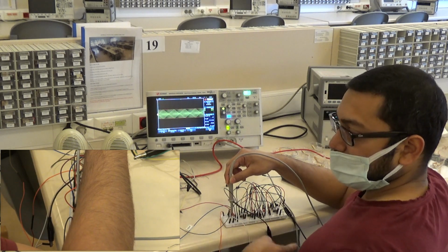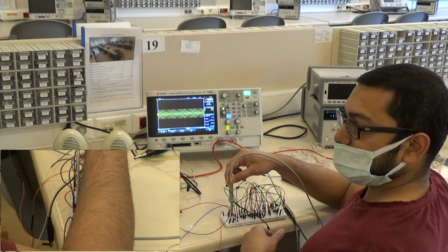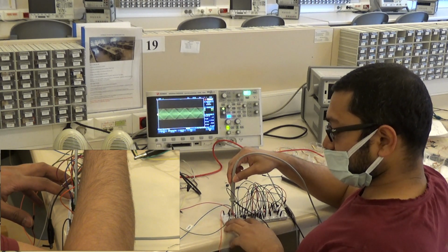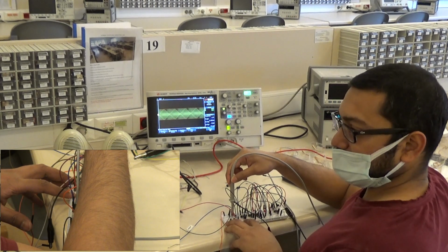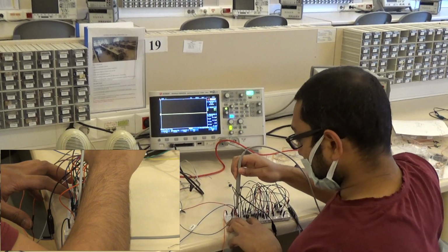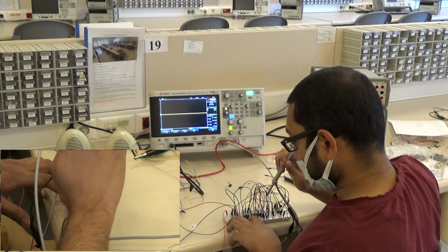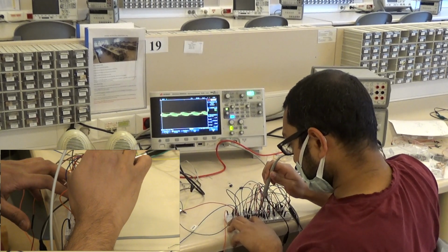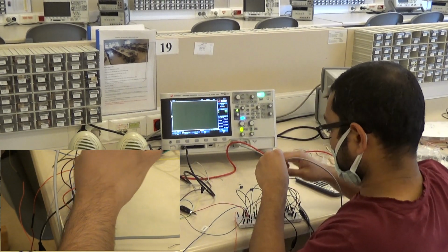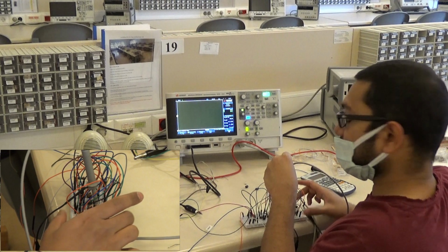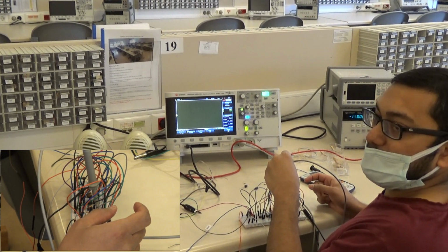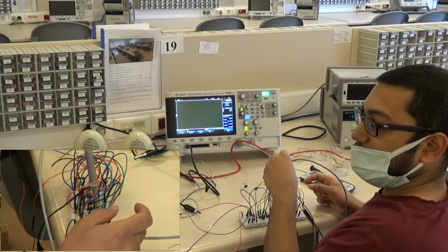Since the voltage transmitted from the antenna is not that small, I have chosen a gain of around 66, 67, but actually we need more than 100. Now, the amplified version is what you can see right now. It's a 3-stage amplifier, and we have used the TL081 IC.